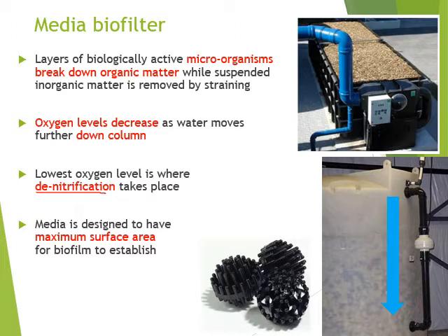We're not discharging them, so it's not that relevant. But if you were to use this system in an ornamental farm that's not recirculating or wants to discharge, this would be insufficient because it doesn't have enough of an aerobic condition to remove the nitrogen completely. So it wouldn't be a solution in and of itself in that context.